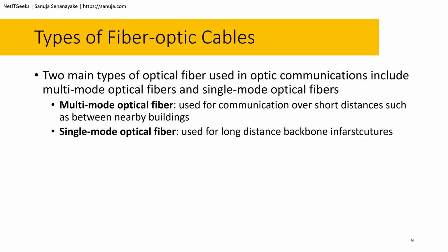So to briefly go over them, what you need to learn, what you need to understand as a junior IT technician, as a junior cable installer or a structured cabling technician, is that multi-mode optical fiber is used for communication over short distances such as between nearby buildings, while single mode optical fiber is used for long distances such as the backbone infrastructure. Single mode optical fiber is used between countries, for example, between Japan and the rest of Asia, the United States and the United Kingdom, like with the submarine cables, etc.